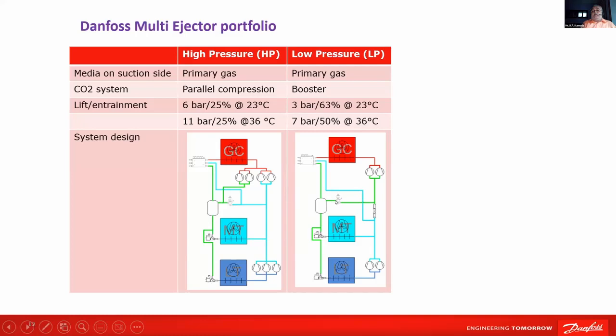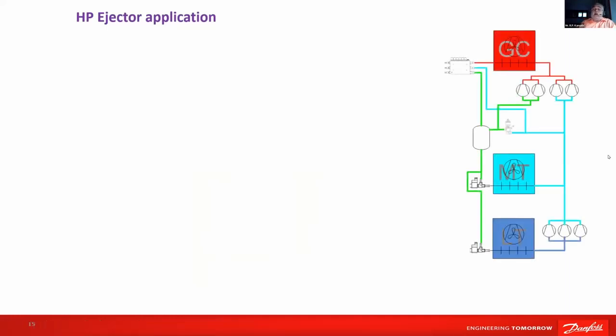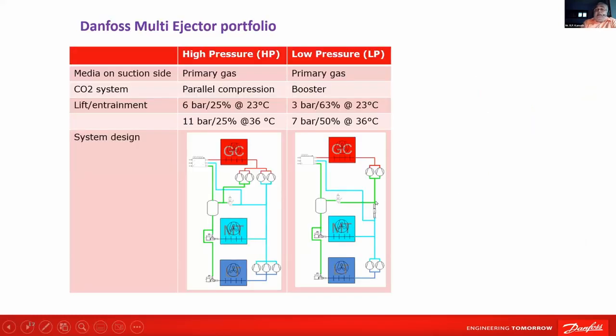This gas bypass valve will reduce the pressure and give it here. No, I'm sorry, I completely confused. This non-return valve will make the difference between the MT evaporator outlet and the suction. So this compressor sucks only at elevated pressure. Now the advantage here, okay, I'll get into that in the next slide.